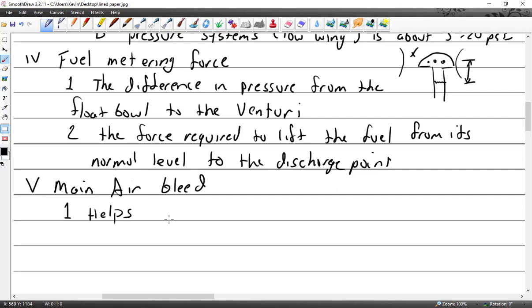There's a huge distinction when we talk about a little bit of air. If we're talking about the idle circuit, we're talking about the main bleed air, so it's a very small amount. So what's the stoichiometric mixture? 15 to 1. How much of this air plays into the 15 part? Zero, about right. So we can't really count that, so make sure we know that.